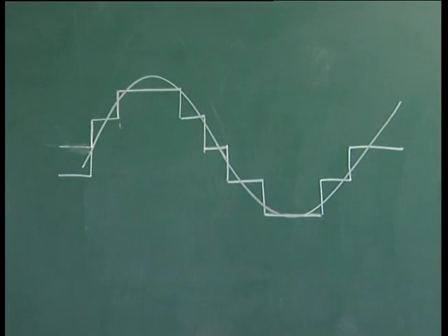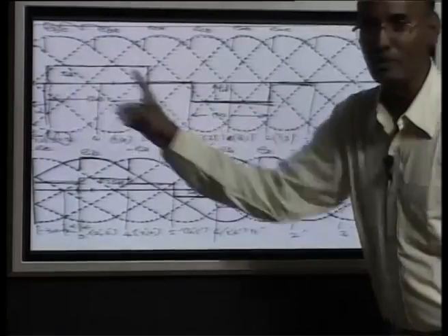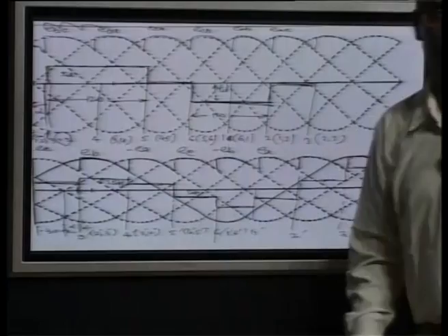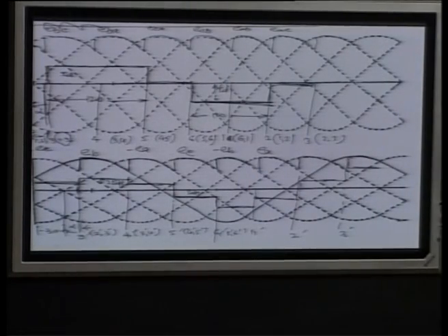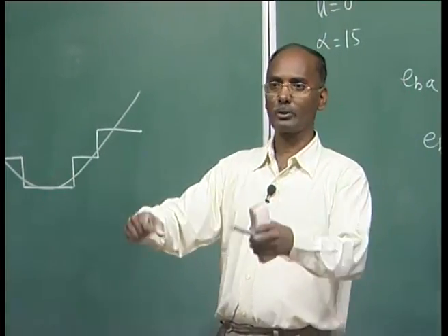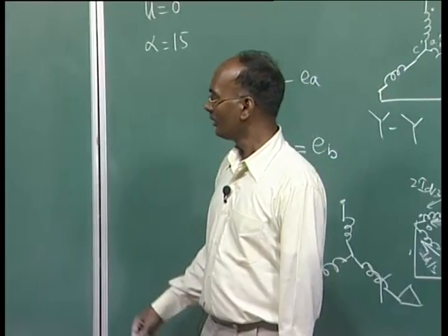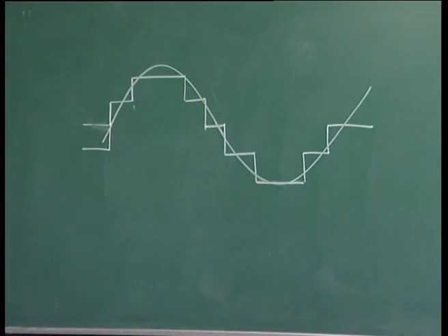Here you can see in this figure we are having the sinusoidal, and here also we are having more harmonics. Due to these two additions, some of the harmonics, as I say 5th and 7th, are cancelled by each other, because one will be positive, another will be negative, and adding together that will be cancelled off. So, this is basically the 12 pulse current, and this is only due to the shifting that is going to take place.